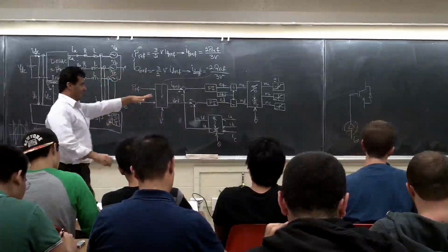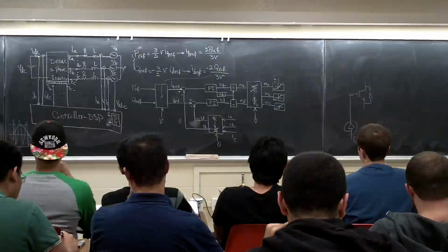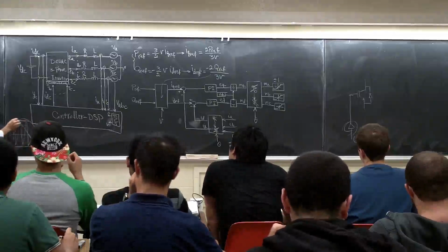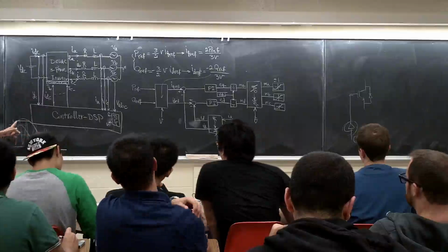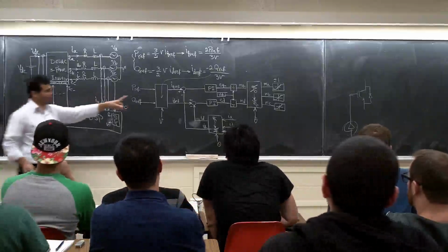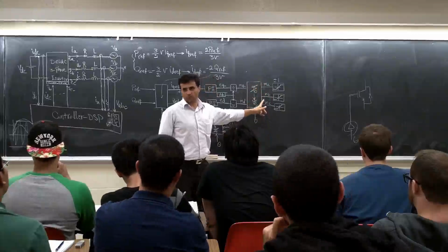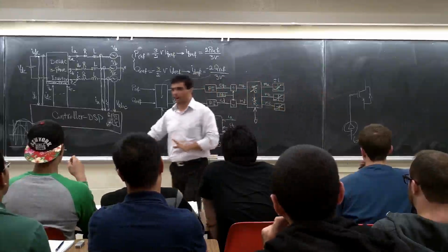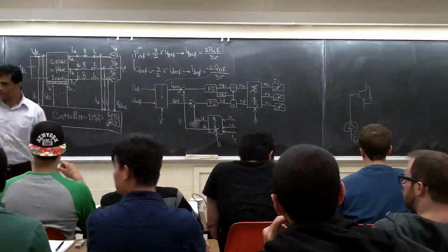For example, this MA is going to be changing, right? This MA is going to be a signal like this. For example, here is 0.2, pass it through. Let's say MA is like this, right? Here you are going back. No, I want this signal. Send me this signal, cut it here. Part of it is going to be sine, but it's going to clamp here, because it's going more than 1. So if the absolute value of this signal is less than 1, it is going to go exactly through, no change. Here and here will be the same. But if somehow they go more than 1 or less than minus 1, it's going to clamp them and keep it there.